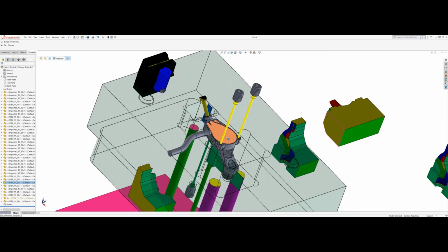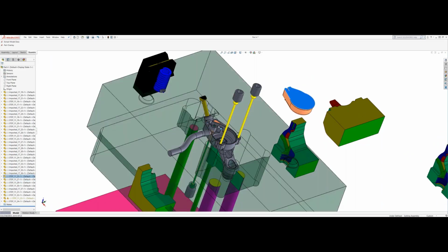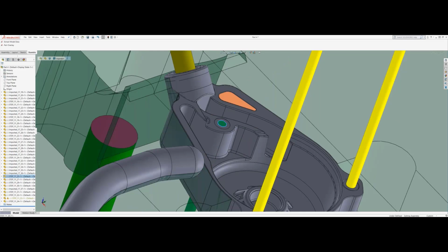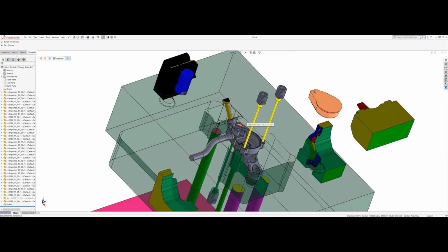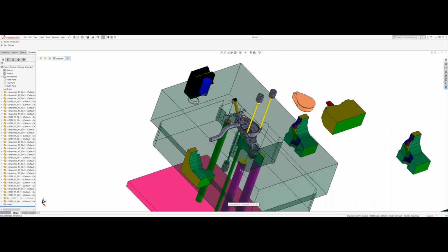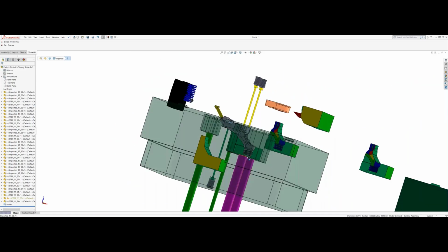And then we had an overmolded insert actually right here, which is this guy. So this is a very busy little part, and this part is roughly about 2.5–3 inches long. As you can see there, we've got ejector pins down underneath of all the hand loads. So this entire assembly ejects out of the tool and then is manually demolded from there. Yeah, which means no ejection on the part. On the actual part itself, correct.